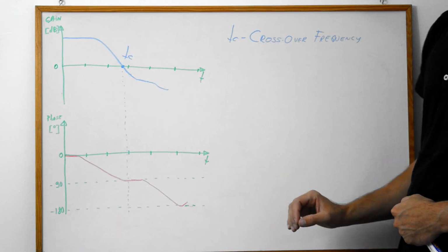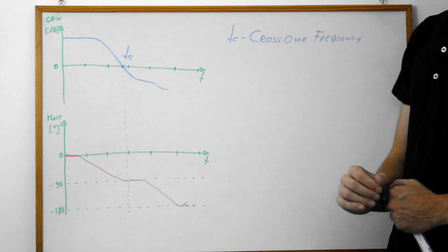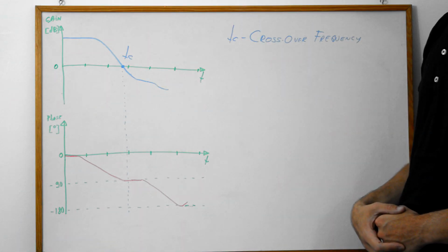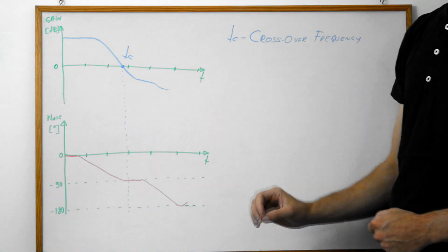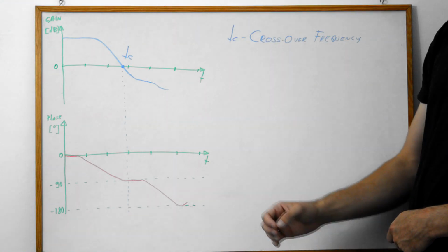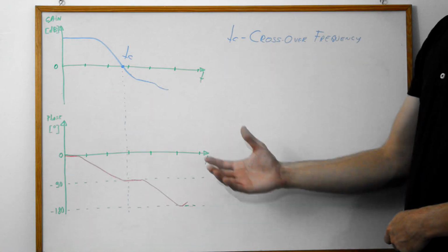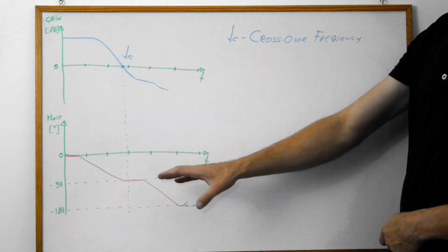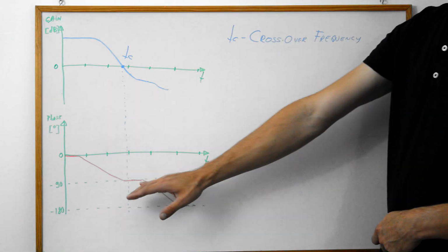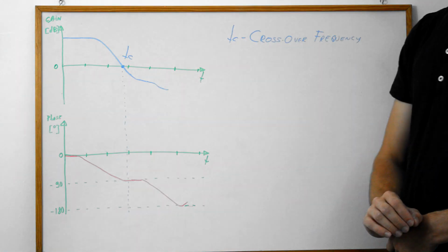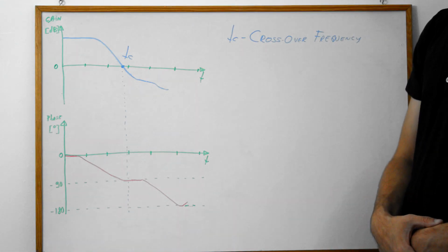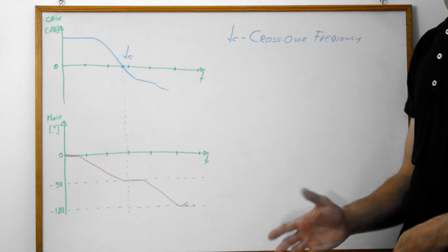We don't want that. The other extreme is 0 degrees. If we inject a signal, we get the exact same signal. If we inject a bit lower frequency, then we're amplifying and amplifying and amplifying, and basically we've built a positive feedback system, which again is something we don't really want. What we do want, on the other hand, is a stable system. And we can get stability only if our response is around 90 degrees. Now, in practice, you will not get perfectly 90 degrees in all cases. I mean, you can get it, but it's not always that easy.